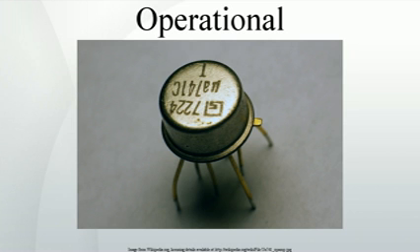Circuit design follows the same lines for all electronic circuits. A specification is drawn up governing what the circuit is required to do, with allowable limits. For example, the gain may be required to be 100 times, with a tolerance of 5% but drift of less than 1% in a specified temperature range. The input impedance not less than 1 megohm, etc.